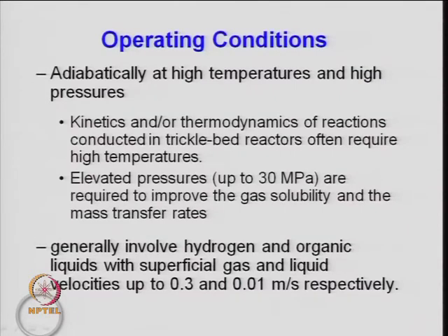Operating conditions: generally the trickle bed reactors are operated at high pressure. Solubility is one thing, and thermodynamic criteria is another thing, which requires a high pressure for this kind of operation. So, high temperature and high pressure. Temperature is governed by the thermodynamics which is required, and the same thing for pressure, and pressure is also required to increase better contact between gas and liquid.